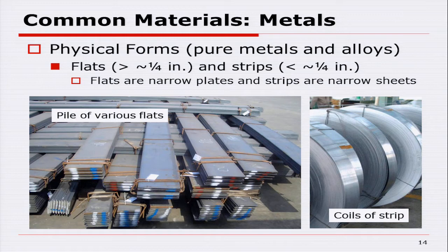And having that sharp edge is not a problem in our lab, because when we're working, we will come in and take a grinder and take off that sharp edge. We want to do that because sharp edges are dangerous if you come in contact with a sharp metal edge. Also, paint doesn't adhere as well to that sharp corner.